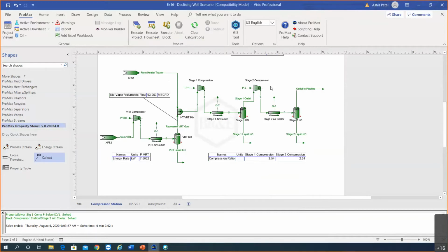And so in order to actually see or compare those economic effects, we use a tool in Promax called the scenario tool. The scenario tool is a tool in Promax that allows you to run case studies. Like in this case, we're going to be running an economic case study by having input variables in Excel plug into Promax, and then the results from Promax being sent back over to Excel.